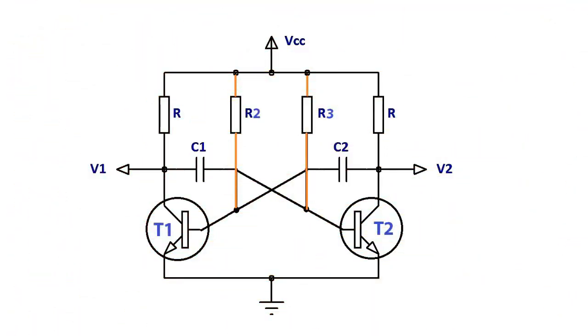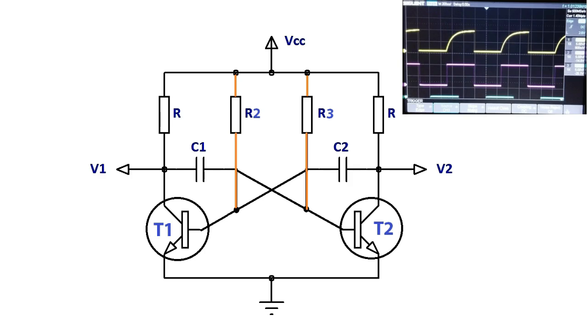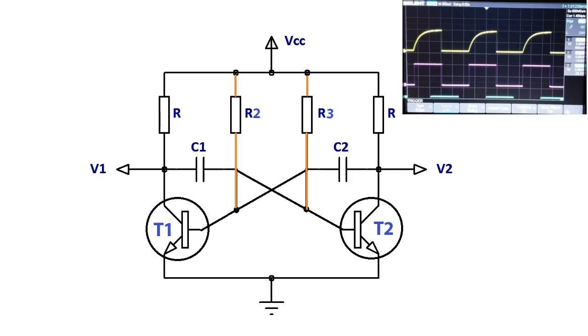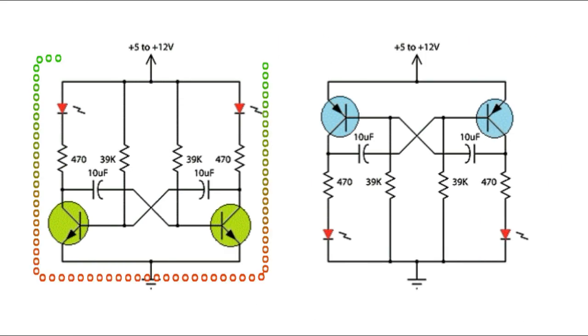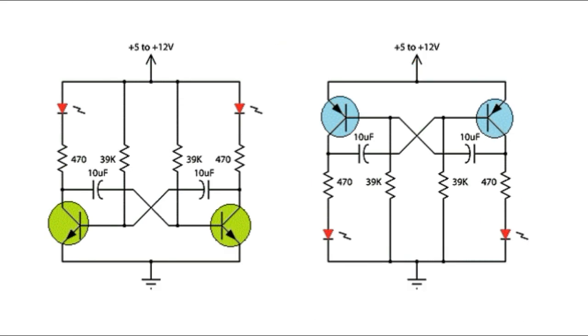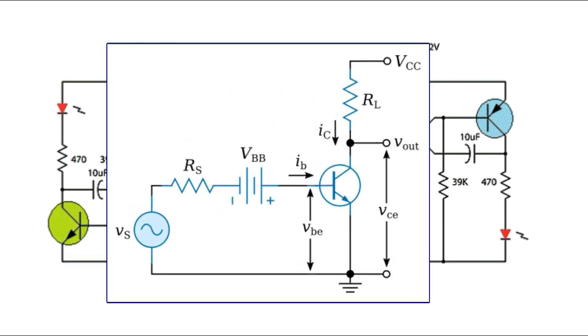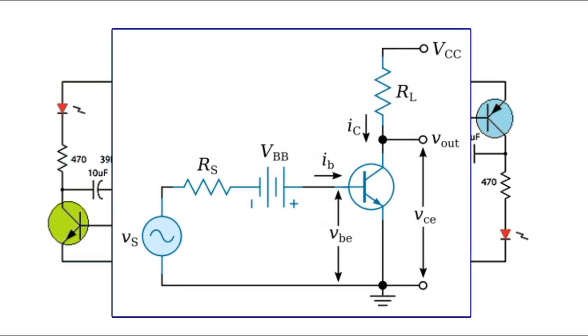The basic transistor circuit for an Astable multivibrator produces a square wave output from a pair of grounded emitter cross-coupled transistors. Both transistors, either NPN or PNP, in the multivibrator are biased for linear operation and are operated as common emitter amplifiers with 100% positive feedback.